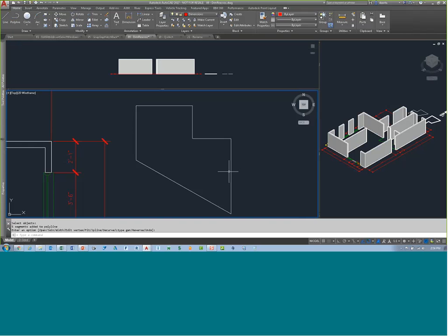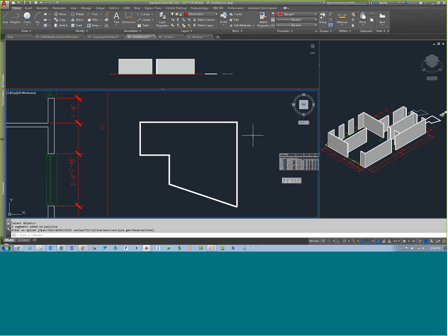If you're working with P-lines, you can hold the control key down and pick a subobject selection. For example, this segment here, because if you don't hold the control key down and you pick the P-line, it picks the whole thing. So you can actually hold the control key down and pick this one particular entity if you need to.